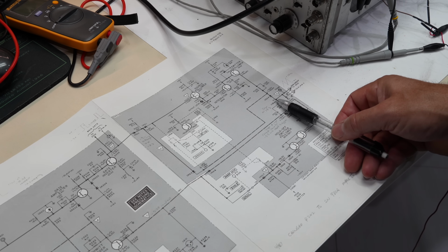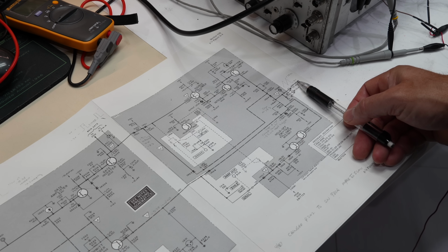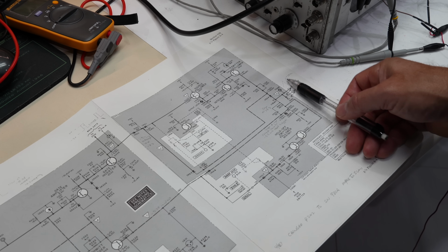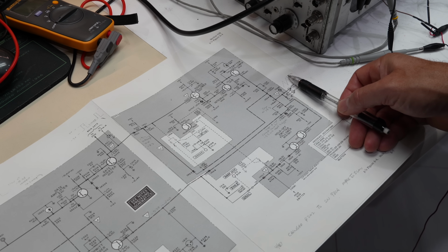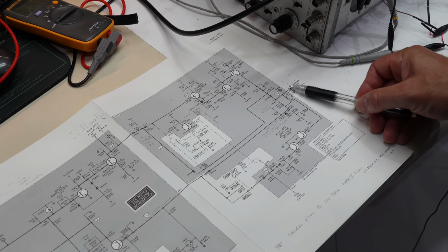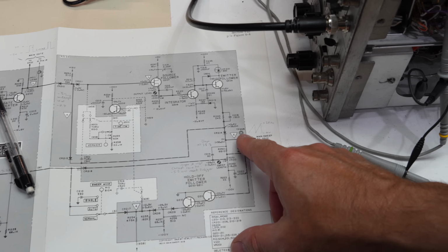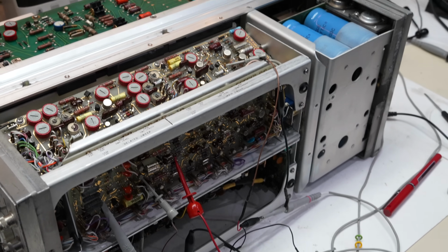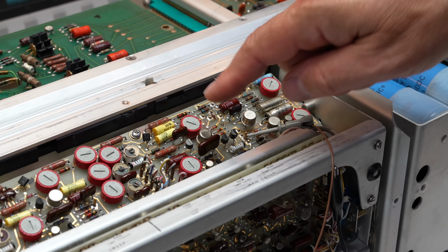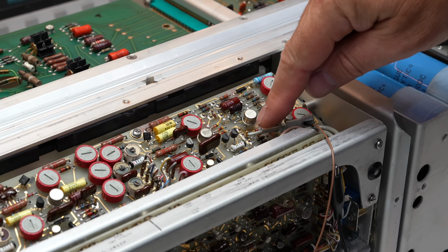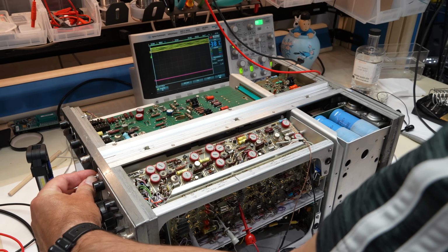But to know that is easy, I just go over here, which is the output to the horizontal deflection, and I'll be able to see where the dot is. It's either stuck at 0 volt or at plus 38 volts. So I'm now going to test at TP205. That's the output of the whole shebang. And finally we move up to the upper card, actually not very far from where we had the previous repair done. And that's the test point.